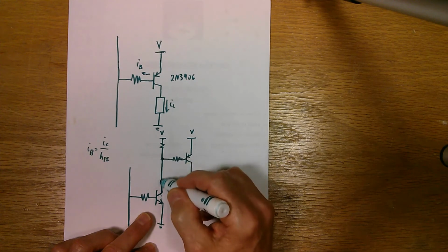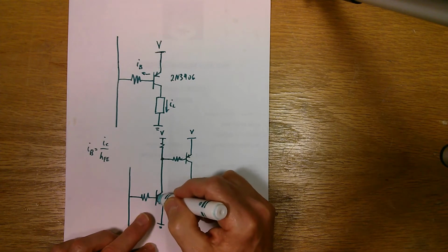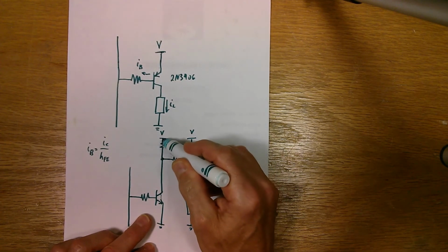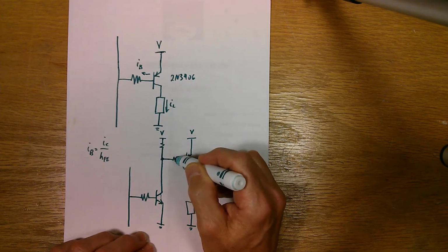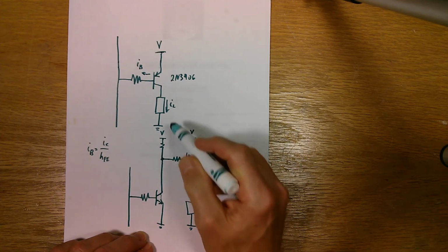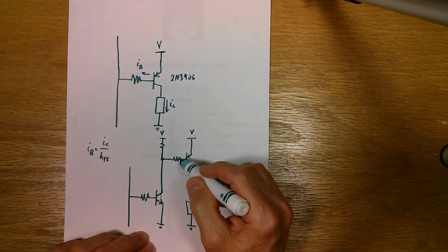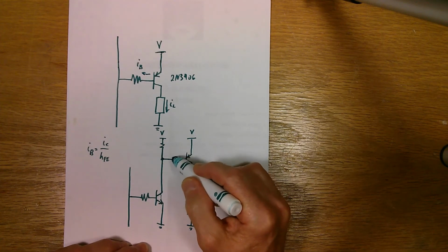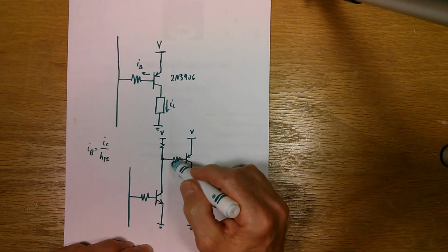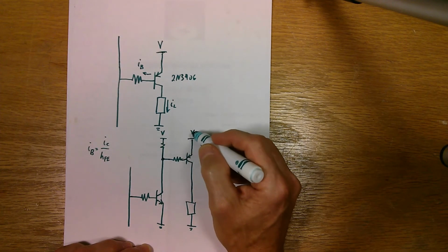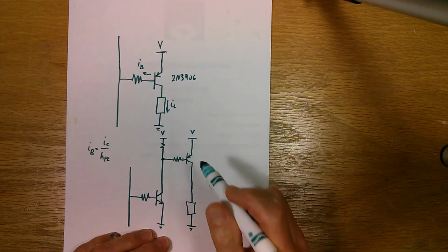Now, obviously, the current flowing in the collector for this transistor is going to be much less than in my previous example. It'll be whatever the current flowing through this resistor is plus the base current here. You calculate the base resistor the same way as you did up here, except your V now is higher voltage. So it's V minus the 0.7 volts here. And so your resistor is probably going to get a bit bigger than if this was a 5 volt. So if this was a 12 volt supply, you'd have a certain value of resistor based on your base current. If this was a 5 volt supply, your base resistor will be much lower.